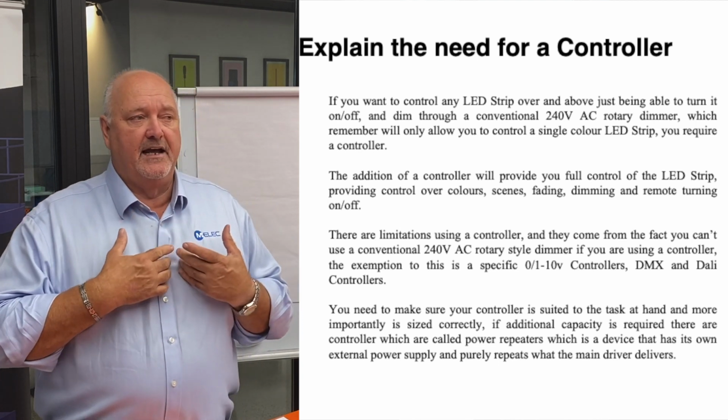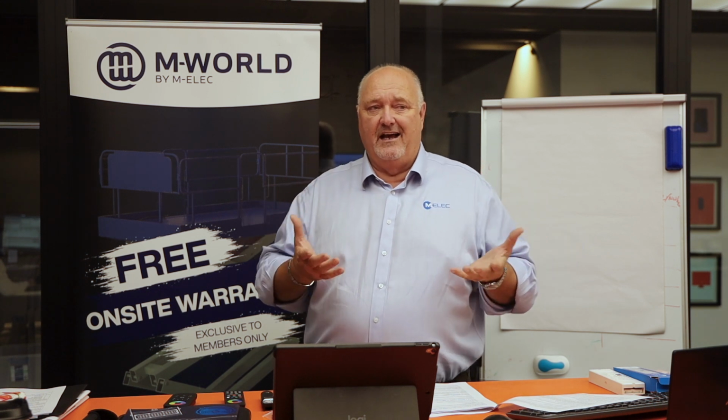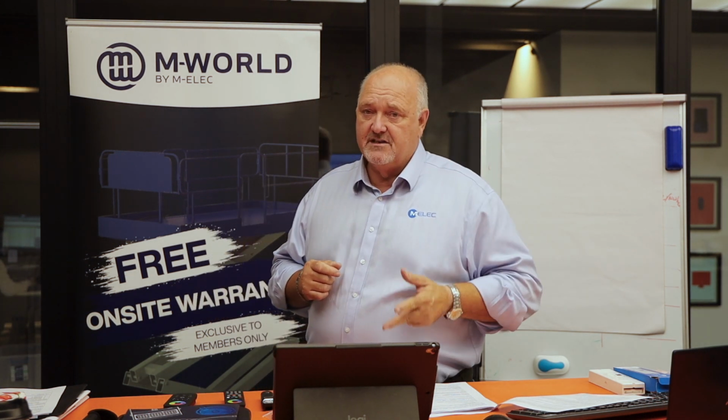So it comes down to the questions that you've got to ask. Basically a controller will provide full control over your LED strip, provide control over the colors, the scenes, the fading, the dimming, the remote tuning, or turning it on and off and things like that. But you've got to have the right controller. Am I using DALI? Am I using 0 or 1 to 10 volt? Am I using DMX? What am I using? You've got to find that out first. Controllers are available to do it, but you've got to work it out yourself first.